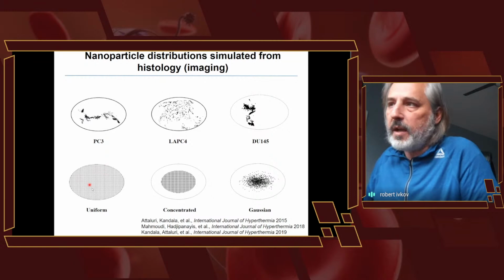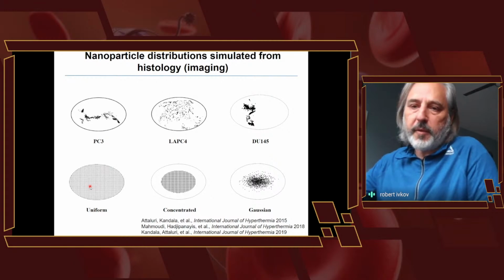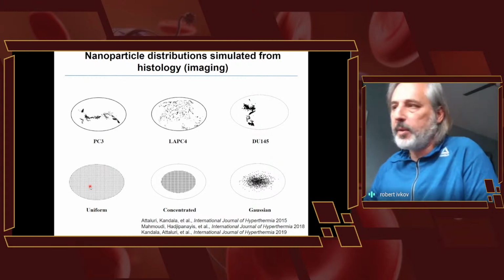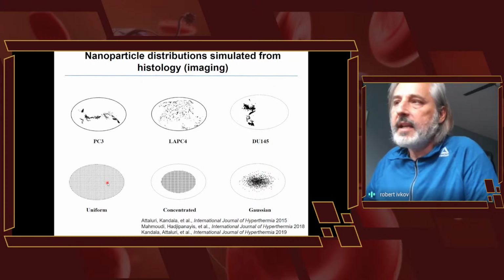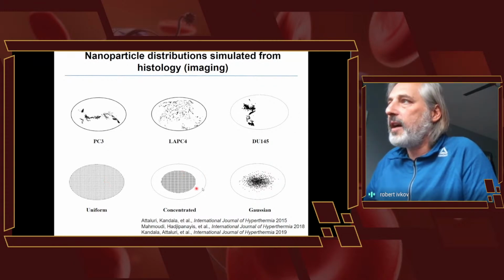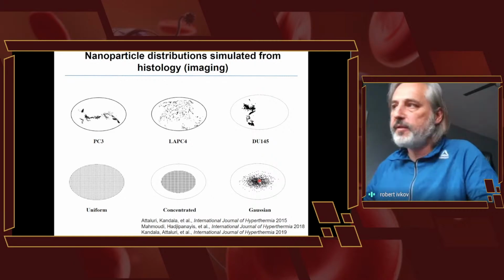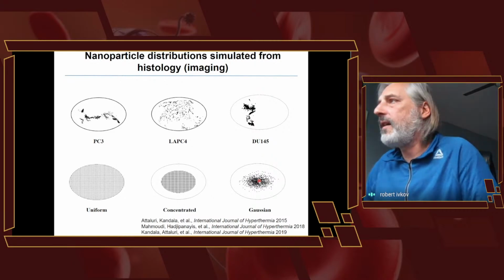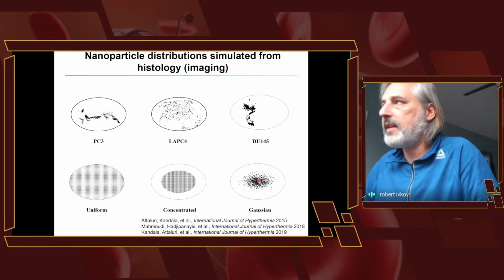the normal tissue. When you take into account heat transfer and the heat transfer properties of tissue, particularly blood flow and perfusion, what ends up happening is that the uniform distribution of nanoparticles is not as ideal as some localized concentrated aggregates of nanoparticles, because now they can generate a great deal of heat, and then you can let that heat transfer out of the tumor. Of course, that implies that one has to use some different strategies for managing that heating. So that question leads into this slide.